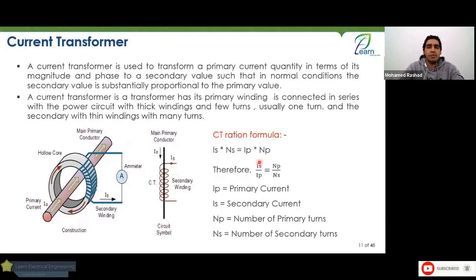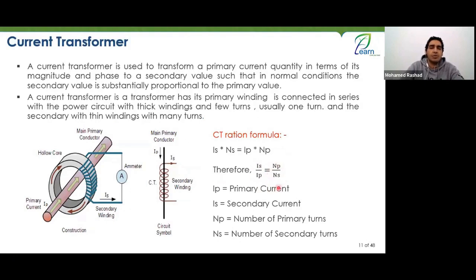And of course, we know that your equation is quite simply that the secondary current over the primary current equals the primary turns over the secondary turns, or the relationship is inverse in the case of the current transformer.